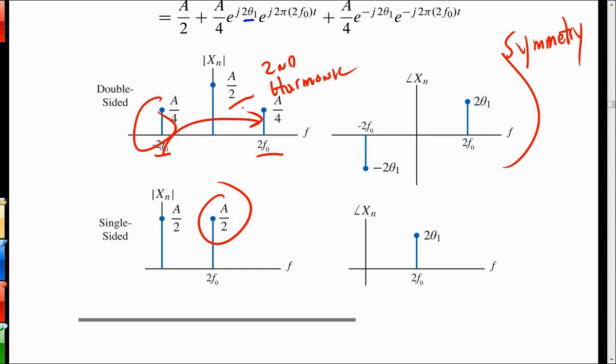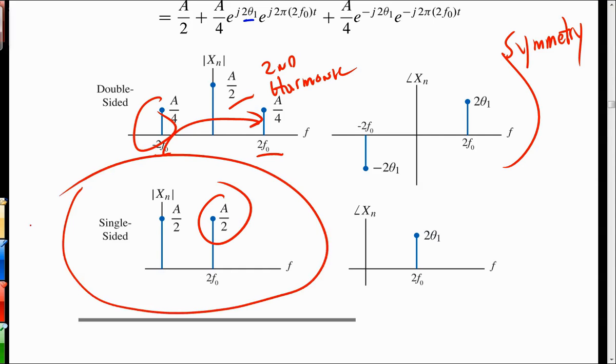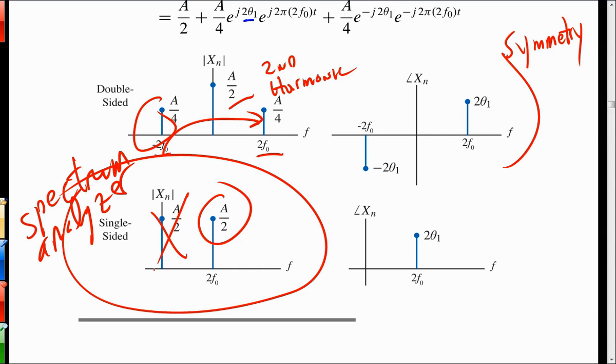And this is the spectrum analyzer model, except the spectrum analyzer won't be displaying the DC component, but it would display the A over 2, and then it displays it in power in dBm in a 50 ohm system. So there's a little bit more calculations in there. For those of you in the lab, though, I've got that in the lab sheet for doing that conversion to go from the amplitude and then the power in dBm in a 50 ohm system.